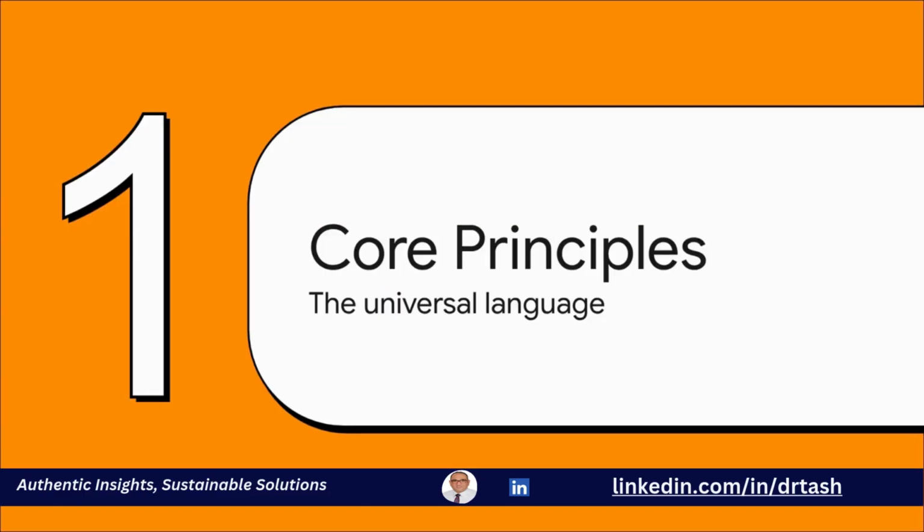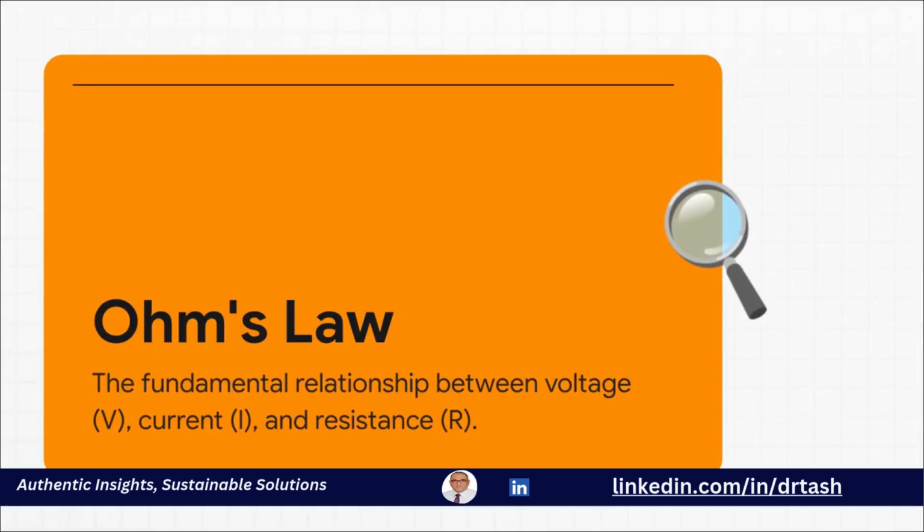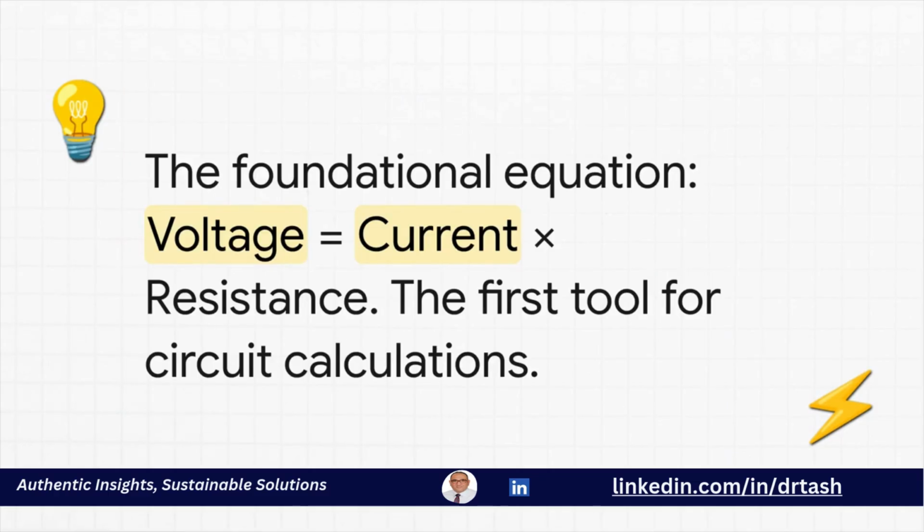Okay, first up, the bedrock. Let's just quickly reestablish that universal language we all use, but let's look at it through the lens of energy waste. Everything we do traces back to good old Ohm's law, but we're not here to just recite the formula. For us, the key is understanding how this fundamental law shows up as waste in the complex systems we manage. So, V equals I times R. For us, this isn't about solving a simple circuit problem. It's about diagnosing real-world issues. Think about excessive voltage drop over a long cable run. That's Ohm's law in action, directly hurting equipment performance and, more importantly, piling up our energy losses.